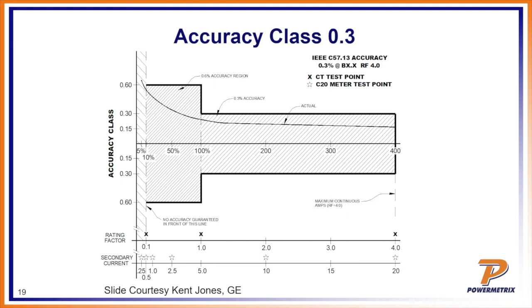Number two reason why I love extended range CTs so much is that it helps with stocking. I've seen these extended range CTs, there are 200 to 5 CTs or 500 to 5 CTs. So all I've got to do is carry one particular CT and then use these for all my installations, because I can use that rating factor. So I can use a rating factor of 4, get 4 times whatever that is. If I've got a 500 to 5 CT, I can get up to 2,000 amps. For 200 to 5, I can get 800 amps. So great product, great for stocking.